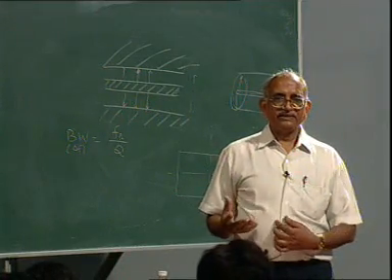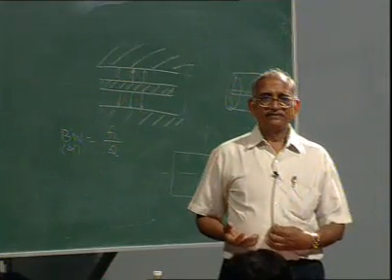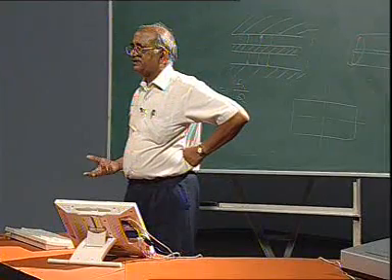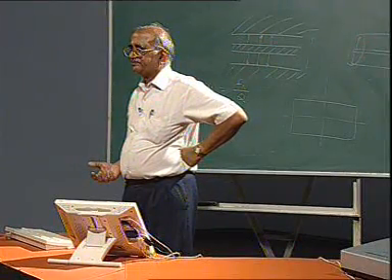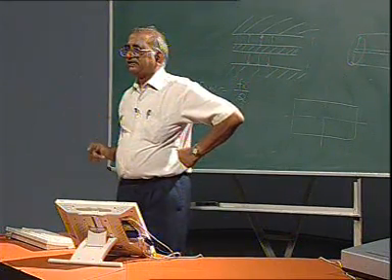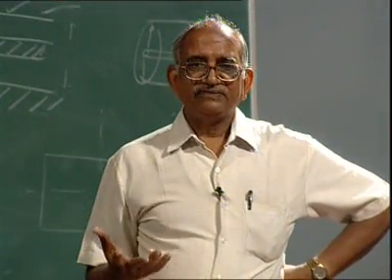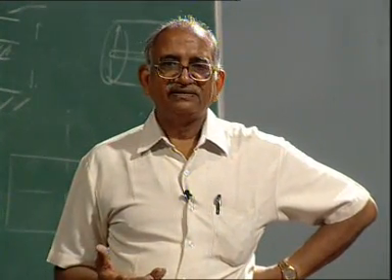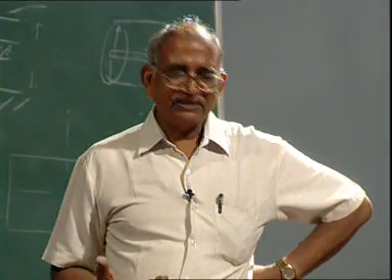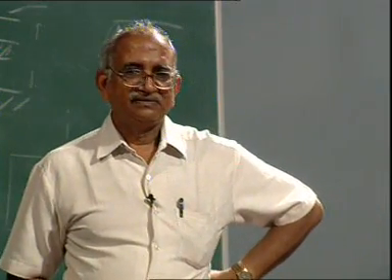If you increase the substrate thickness by a factor of 2, what happened to the energy storage? What happened to the capacitance? Okay, we can put it that way. If you increase the substrate thickness by a factor of 2, what happens to the parallel plate capacitance? Capacitance will decrease, and energy stored will decrease. So, Q should decrease, bandwidth will increase. That okay?